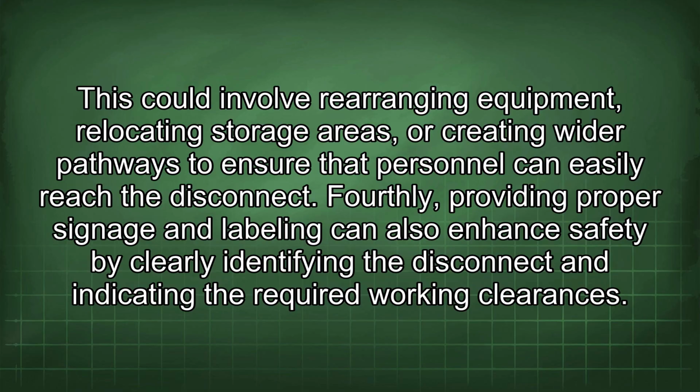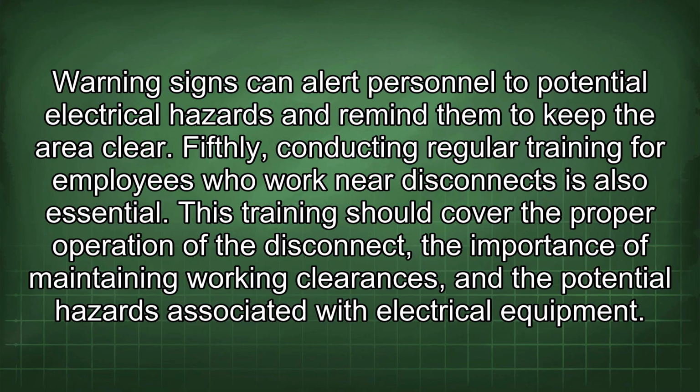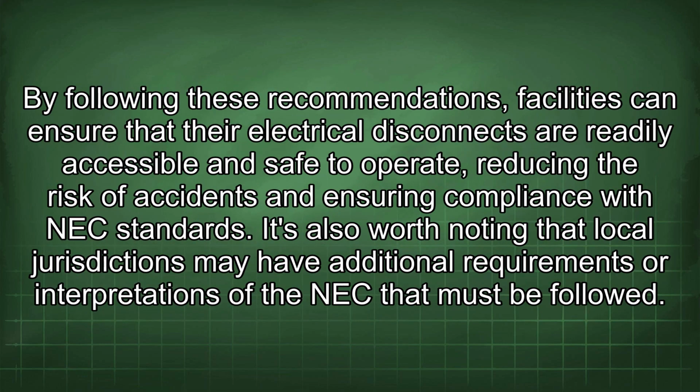working clearances. Warning signs can alert personnel to potential electrical hazards and remind them to keep the area clear. Fifthly, conducting regular training for employees who work near disconnects is also essential. This training should cover the proper operation of the disconnect, the importance of maintaining working clearances, and the potential hazards associated with electrical equipment. By following these recommendations, facilities can ensure that their electrical disconnects are readily accessible and safe to operate, reducing the risk of accidents and ensuring compliance with NEC standards.